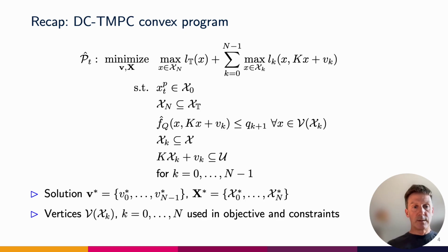So these inequality constraints, which are expressed here, define a tube or a sequence of sets that bound the predicted state trajectory. So now we predict and optimize over a tube, making this a tube MPC strategy. Otherwise, the basic formulation is the same. We solve this problem online at each time step, and we use the optimal solution, the first element of the optimal sequence, to define a predictive control law.